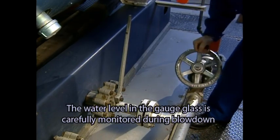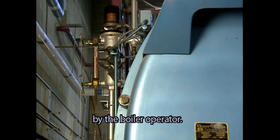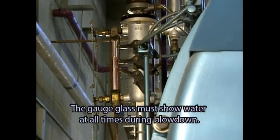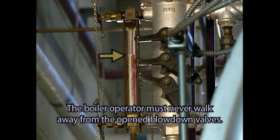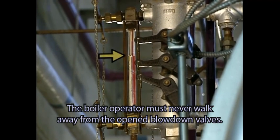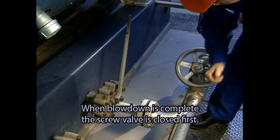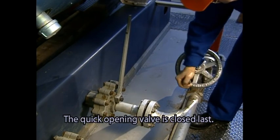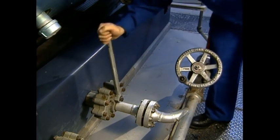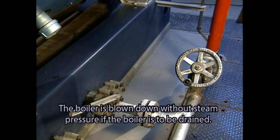The water level in the gauge glass is carefully monitored during blowdown by the boiler operator. The gauge glass must show water at all times during blowdown. The boiler operator must never walk away from the opened blowdown valves. When blowdown is complete, the screw valve is closed first. The quick opening valve is closed last. The boiler is blown down without steam pressure if the boiler is to be drained.